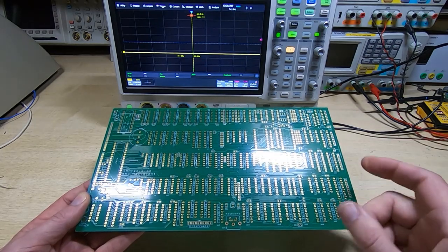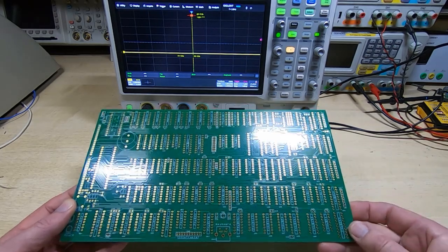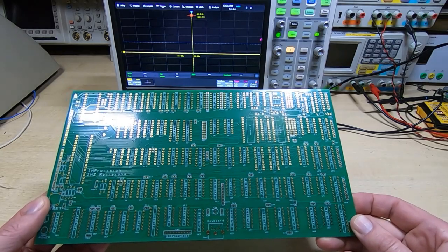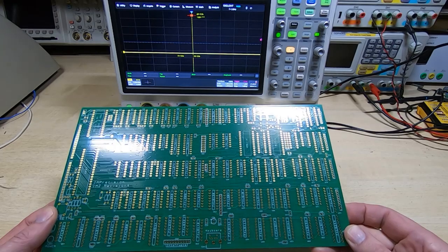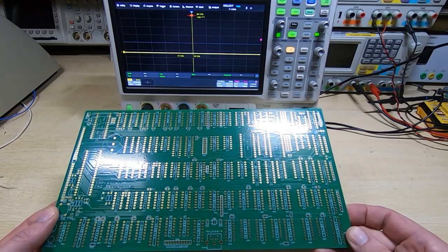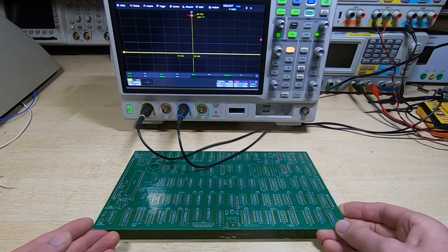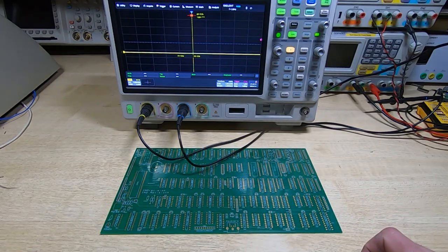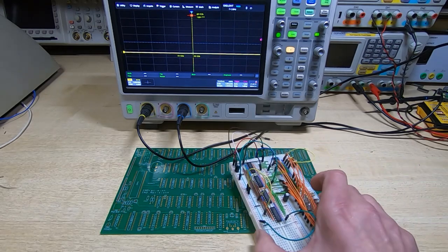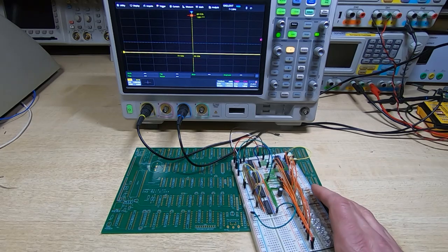We can't really do it in small steps, because what we need to add to include our floppy drive control system, bear in mind I want to include DMA in the control, is we have to add a number of circuits. Firstly, the floppy drive interface that you've seen already, but for the DMA we need to add a loadable 16-bit counter.